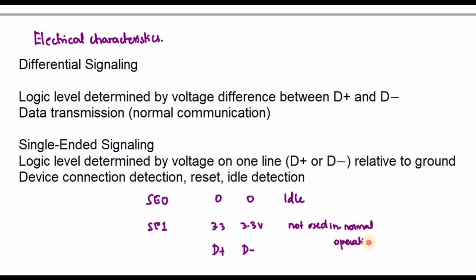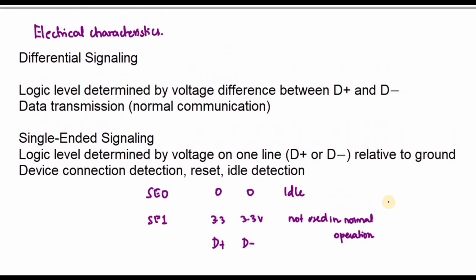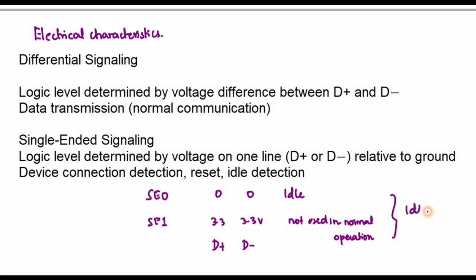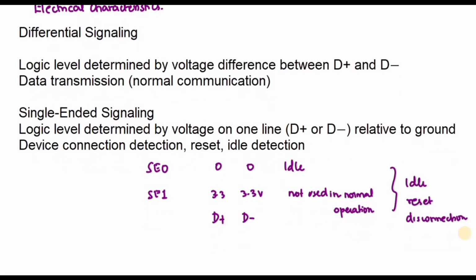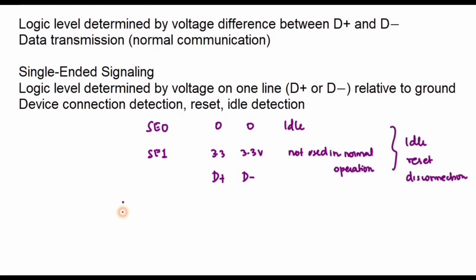Therefore, we go for the alternate arrangement called differential signaling. Here D plus and D minus are used in order to send 1 and 0, and the ground wire is not used here. The receiver will sense the voltage difference between the two wires without reference to the ground.